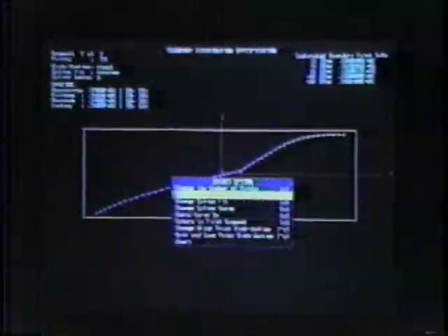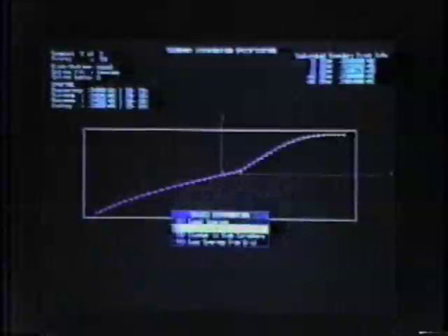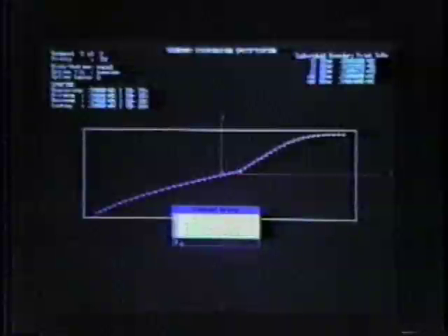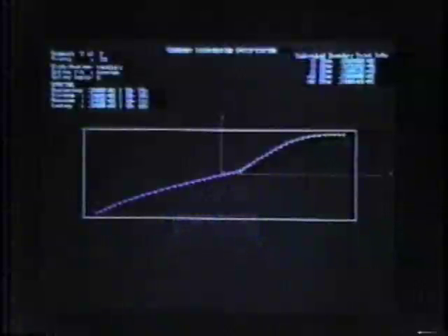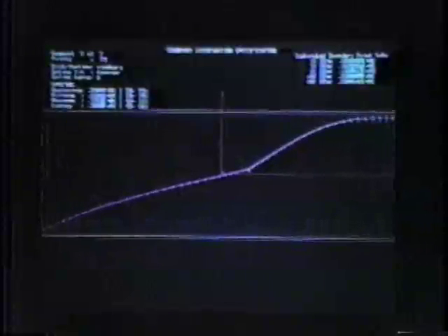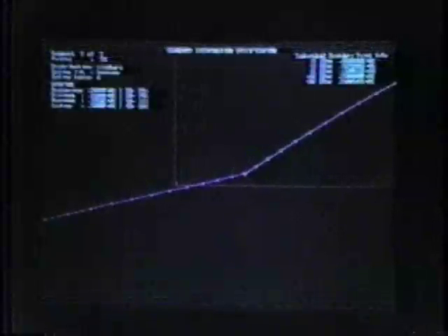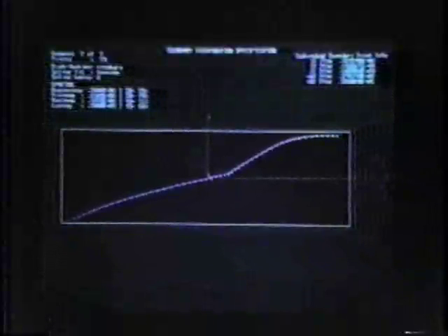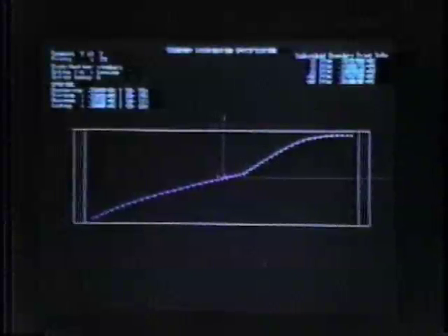These points traced from the F-16 database are then splined to provide a continuous representation of the boundary shape, and grid points are distributed among the continuous boundary. Any of 4 different clustering functions is used to distribute a user set number of points on each sub-boundary. Here, a 2-sided stretching function is used to provide exact spacing at each end of the boundary. This process is then repeated for each of the other 3 boundaries on the wall.